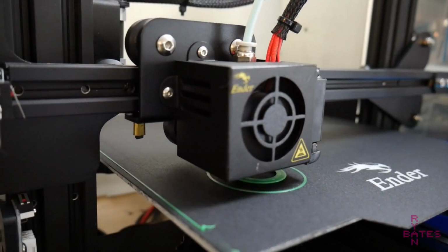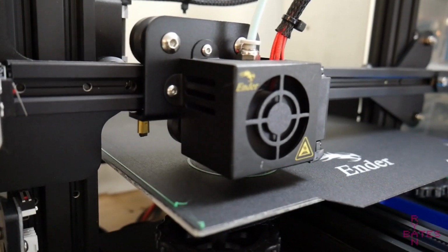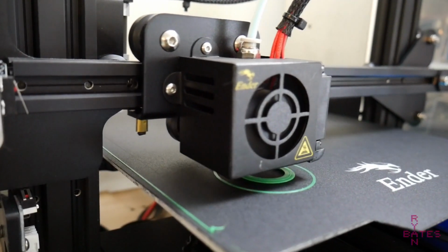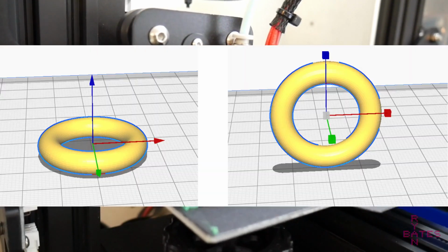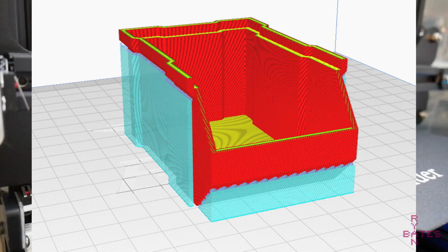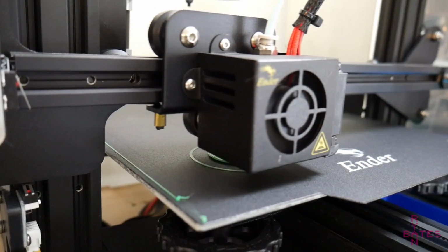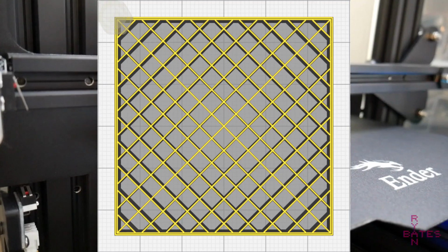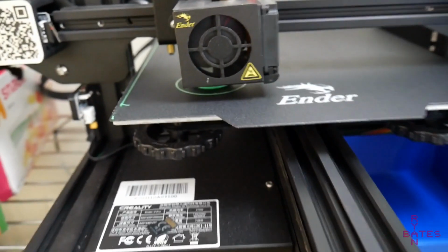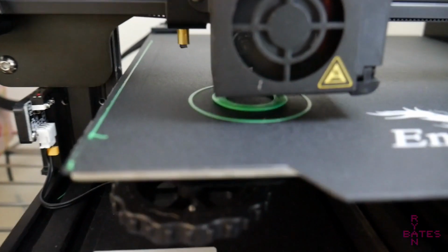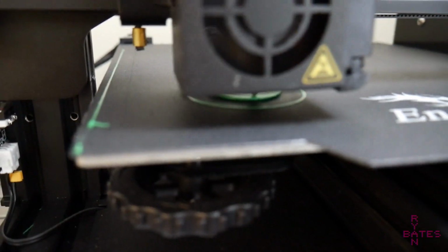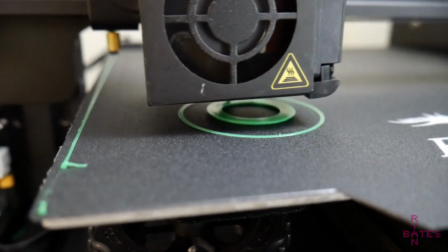You now have enough exposure to be successful with 3D printing, in particular using 3D printing slicing software. In summary, we talked first about the basics: orientation, overhang, scale, and supports. Then we went into more advanced topics like print quality, infill, and build plate adhesion. This video condensed a lot of topics that might take time to grasp, but don't be afraid to revisit a topic again, and above all, experiment with the slicer software.